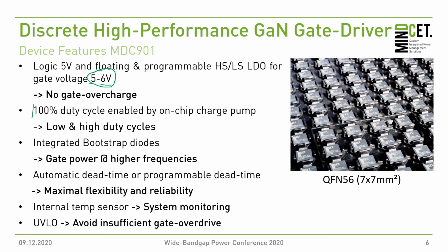Another unique feature of our gate driver, the MDC901, is we are able to reach 100% duty cycle because we have an on-chip charge pump. Apart from 100% duty cycle, this also allows for very low and very high duty cycles, which otherwise would not give your bootstrap enough time to charge the bootstrap circuitry. Nevertheless, we also have internal bootstrap diodes that are really very efficient and can work at high frequencies and provide gate power at high switching frequencies if needed.